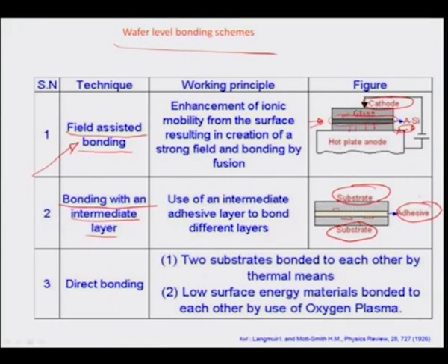So, therefore, they are only used in illustrations where you need to have electrical interconnects or something in that order between the different layers, and BCB in fact is a material which is used in bonding between different substrates in microelectronics off and on, and so different layers can be bonded using BCB bonding technology.